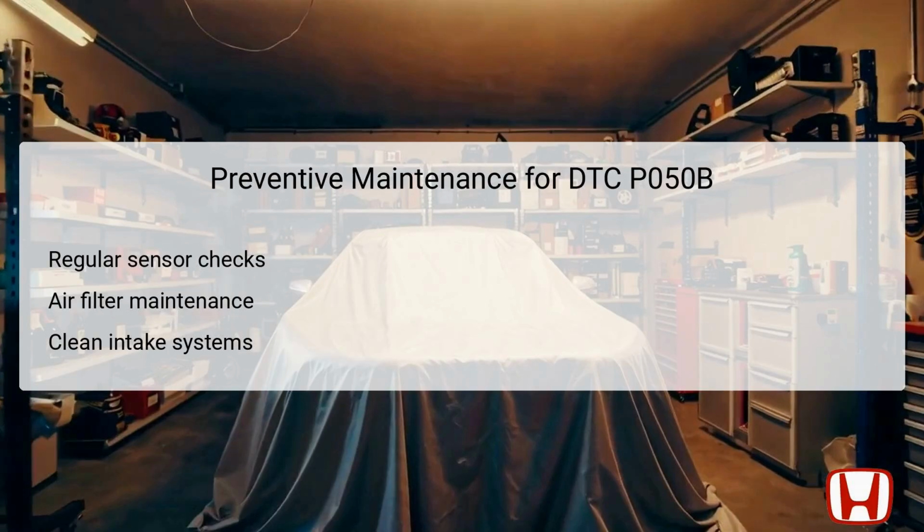Additionally, maintaining clean air filters is essential. Changing the air filter at recommended intervals prevents dirt and debris accumulation that could affect airflow. Cleaning intake systems, including the throttle body, can further enhance air quality entering the combustion chamber. Establishing a consistent maintenance schedule focused on these areas not only extends the life of engine components, but also optimizes